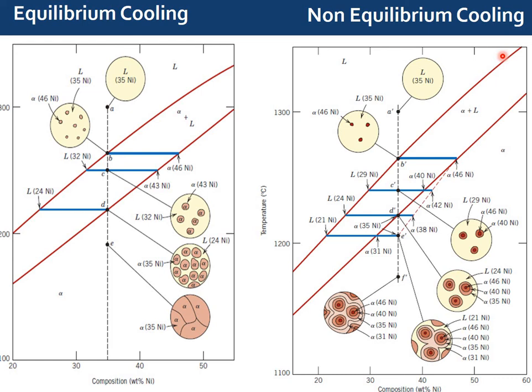For example, in equilibrium cooling, we cool at a fixed rate, that is 10 degrees per minute, or 15, or 5 degrees per minute. But in non-equilibrium cooling, the rate is too high, around 50, 55, or 60 degrees per minute, and the rate may also be changing. We'll be visualizing some pouring in this.